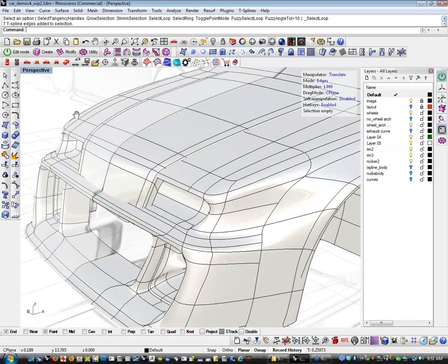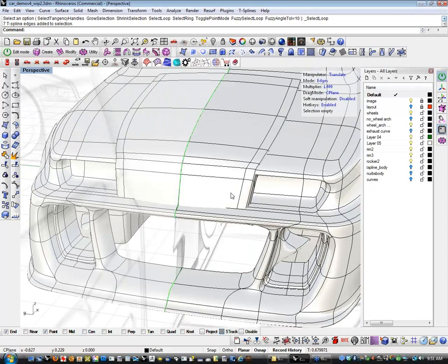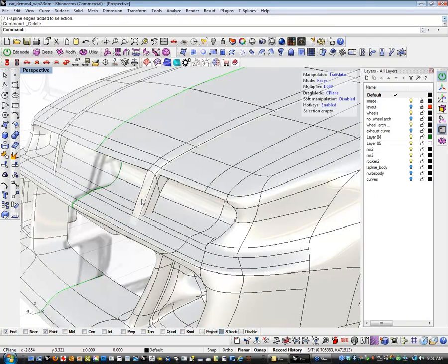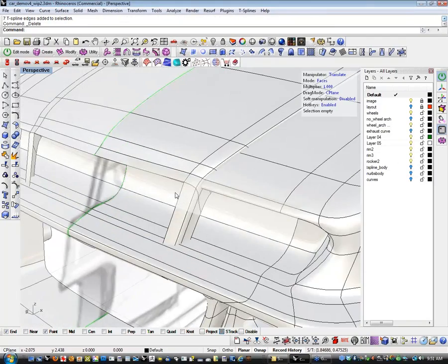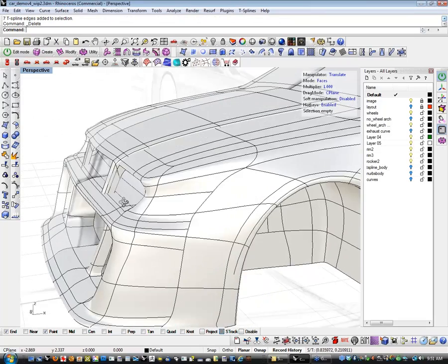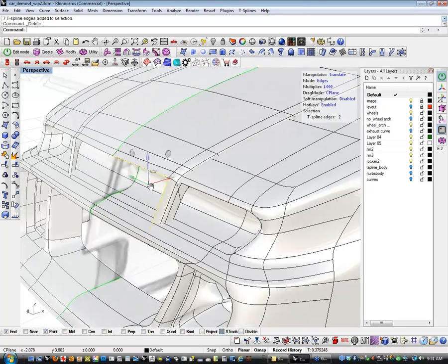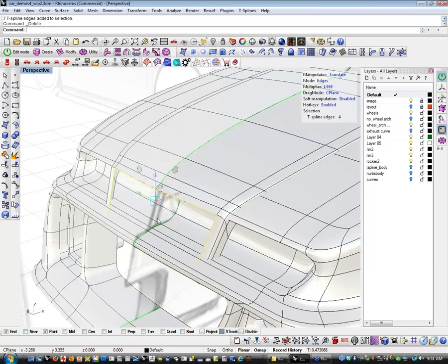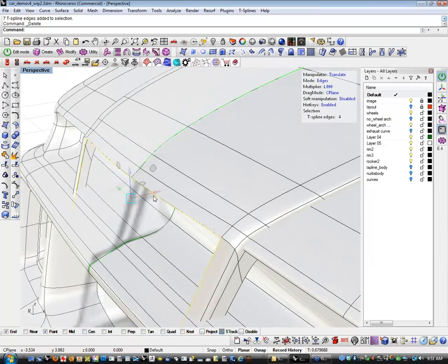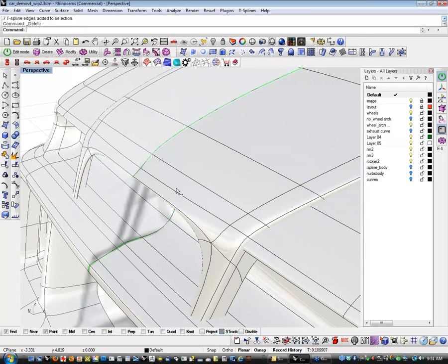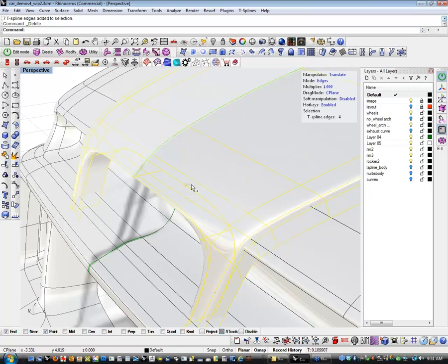All right. So I've already got a hole here waiting to happen because I've got two faces here I can delete. So I'm just going to kill those. And again, when you do that, realize that you've created an unresolved inside edge here, which is going to throw a crease through the model. All you have to do to fix that is just extrude that edge. That edge will resolve, and your smoothness will come back.